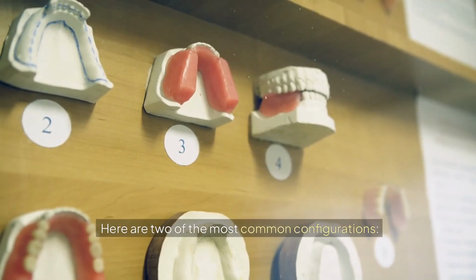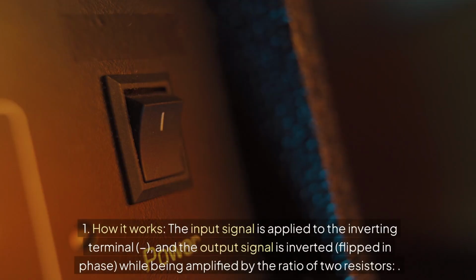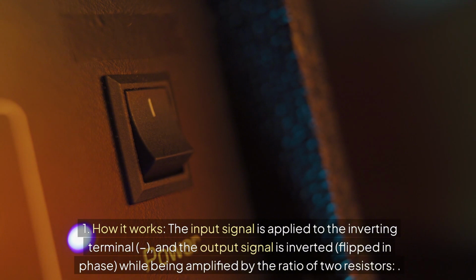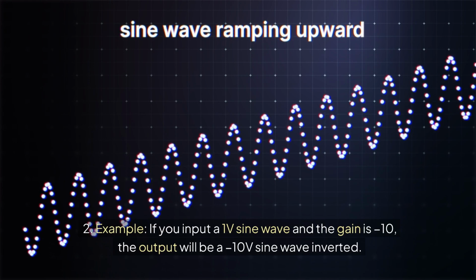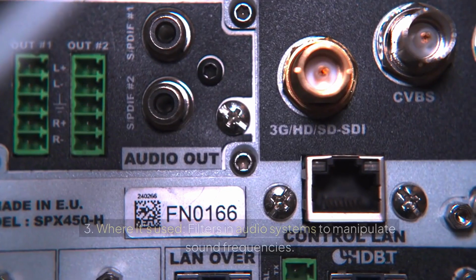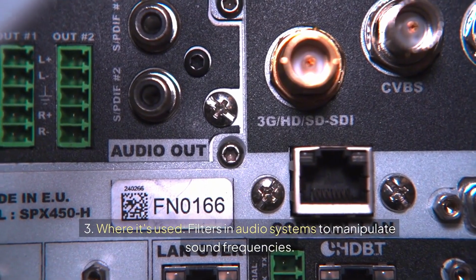2. Basic configurations: op-amps are versatile and can be configured in different ways to achieve specific purposes. Here are two of the most common configurations. Inverting amplifier. 1. How it works: the input signal is applied to the inverting terminal, minus, and the output signal is inverted, flipped in phase, while being amplified by the ratio of two resistors. 2. Example: if you input a 1V sine wave and the gain is -10, the output will be a 10V sine wave, inverted. 3. Where it's used: filters in audio systems to manipulate sound frequencies.